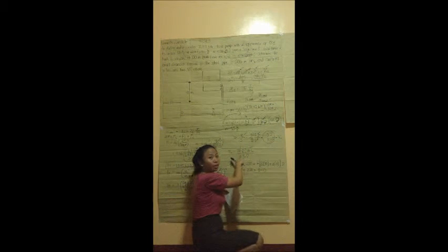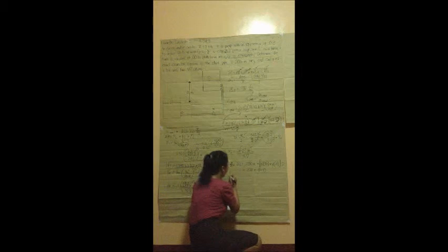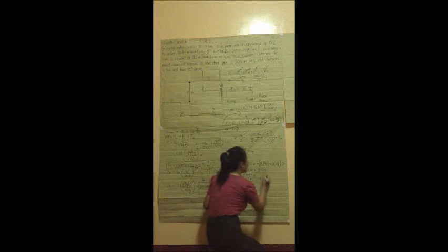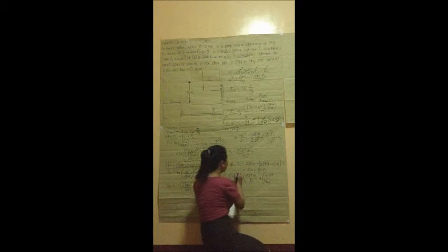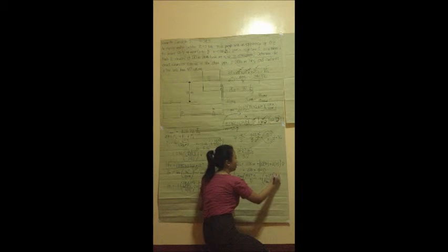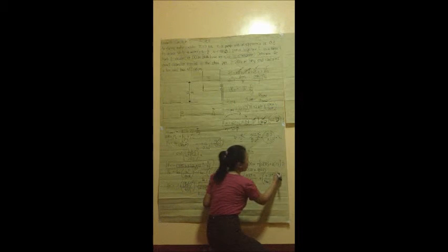We're left with the value of the friction factor F. So the friction factor F has the formula negative 4 log times 0.27 times the roughness parameter over the diameter plus 7 over the Reynolds number raised to 0.9, and then this whole equation raised to a negative 2.